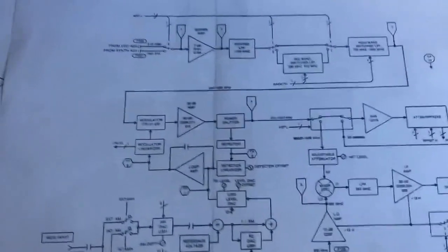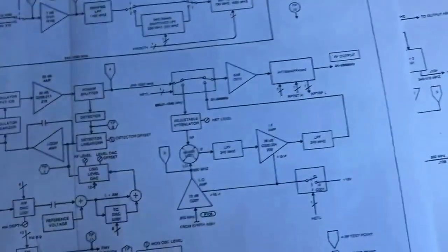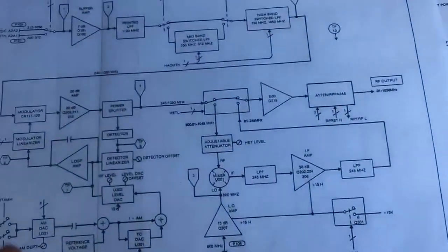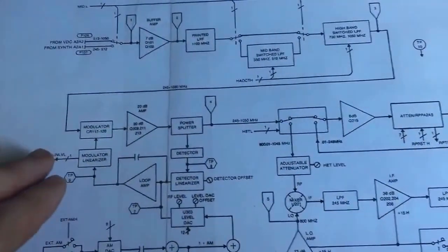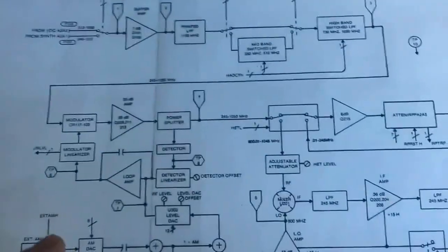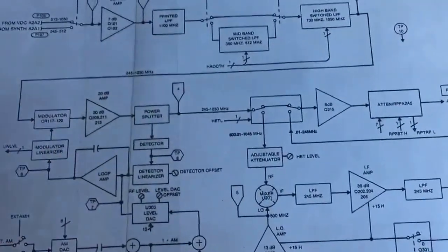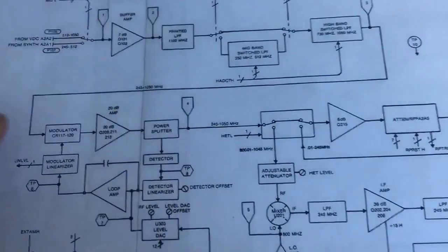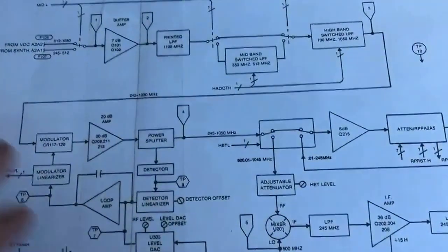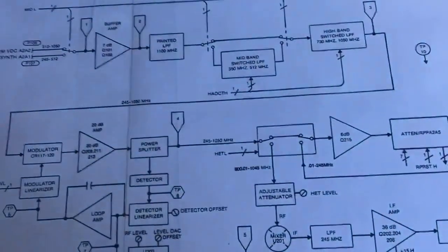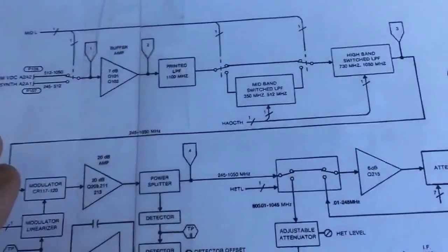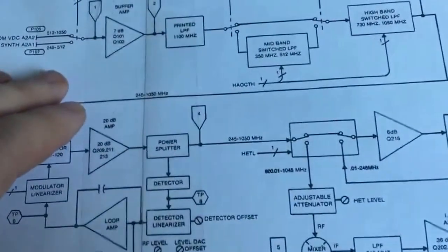Okay, just had an idea. I remember I've seen that the frequency is often out by 20 megahertz, at least on the lower band. And I remember that I'd seen it being out by 10 megahertz. So I thought I'd just go through the frequencies again. Now I've got a bit more of an idea of what I should be looking for, knowing about the other flip-flop which has failed, which is causing unlock. So I can ignore that section of the issue.